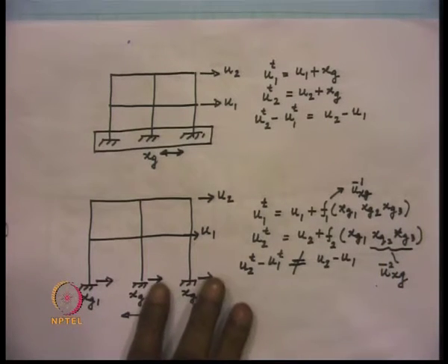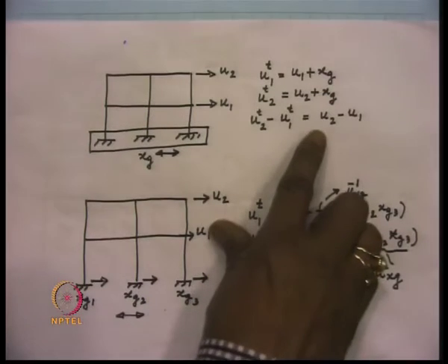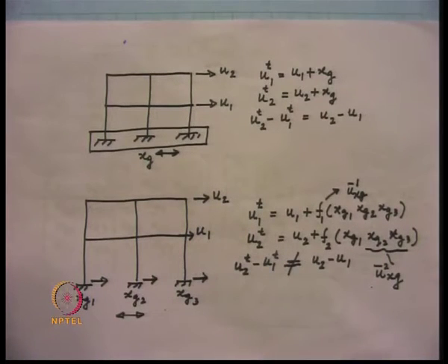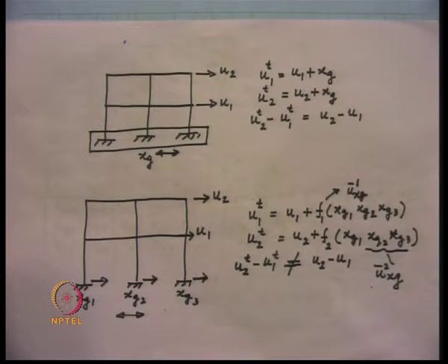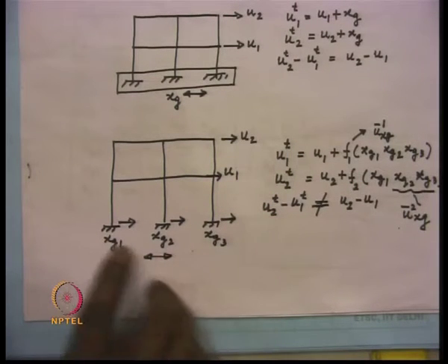We can write down the equation of motion in terms of the relative displacements. And that is why for single support excitation we have written down the equation of motion in the relative displacement coordinate with the right hand side having the mass times acceleration, and this is of course pre multiplied by the influence coefficient vector. Now, when we come to the multi support excitation, then we see that the ground displacements that are there are different at different supports.